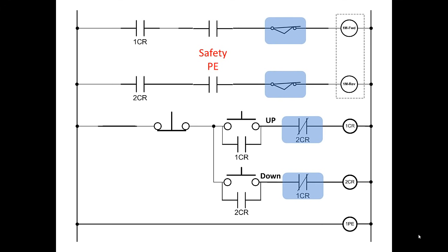So you may be expecting it because you're the engineer and you designed it that way. But the operators are not expecting that door to continue coming down when you remove the obstacle. And everybody knows that owns one of these, just try to cheat it. Hit the button, run out the door real quick. If you break that beam at all, it stops and it sits right there until you start it again. So let's move the interruption of that photo eye to a slightly different place.